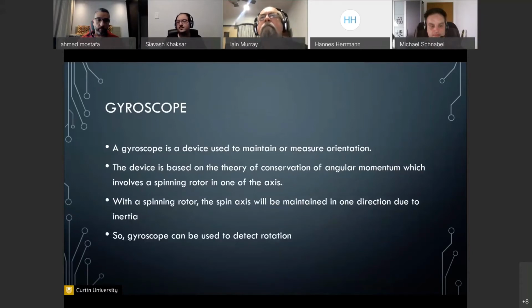We also have the gyroscope in there. The main purpose of that is for measuring orientation. Usually the accelerometer and the gyroscope in an IMU are used together, and we have different orientation techniques to use the data from both of these sensors within the IMU to get our general orientation frame.